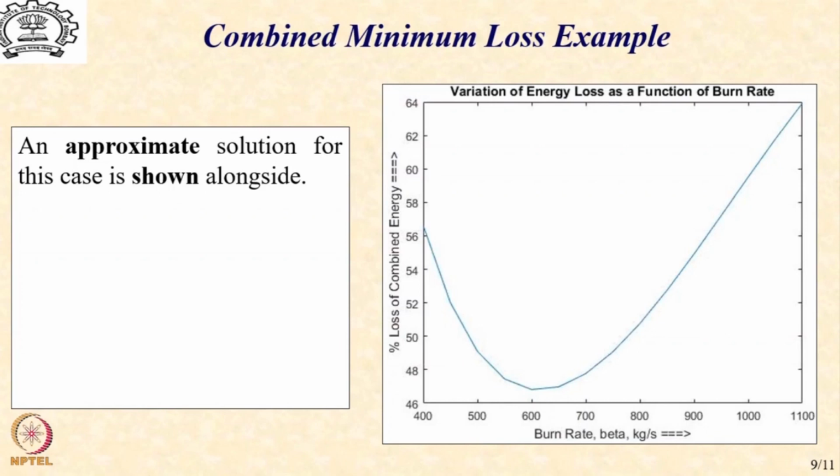Based on that solution, generate the velocity at 12 km altitude, and with that velocity and the density at 12 km altitude, get the value of drag. And once you get the value of drag, you can find out the time taken to reach that altitude, multiply that time taken with beta to find out what is the residual mass at that altitude as a function of beta.